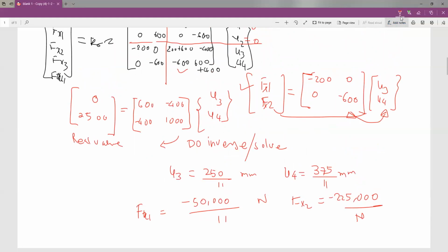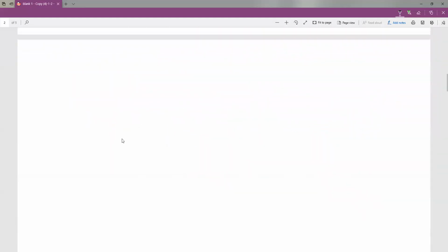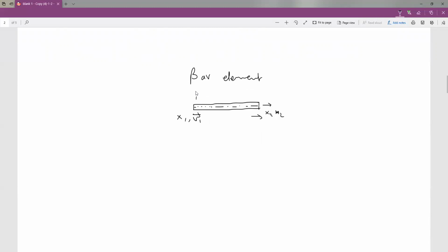Now, even if this was a spring case, I told you that for the trusses and bar system, bar is the element which is subjected to either compression or tension. So, analogy of the spring, this is also an elastic bar, and if we consider x1, u1 as the positive forces and displacement at joint 1 of the bar, and x2, u2 at joint 2 of the bar.